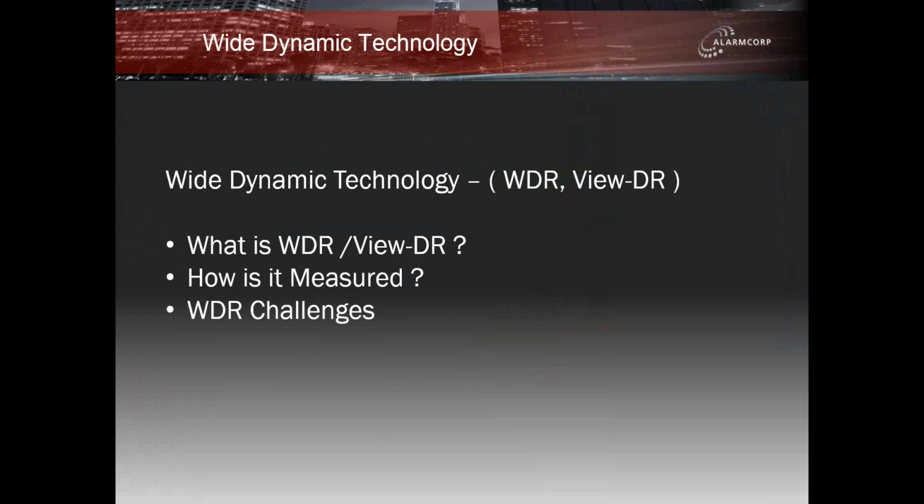Cameras are normally configured in a browser for an IP system at least. A number of manufacturers have their default configurations of enable, disable, or a manufacturer's suggested auto setting. It is also possible to have WDR profiles embedded in the camera. For example, this may be set to a higher value if the backlight is too strong.